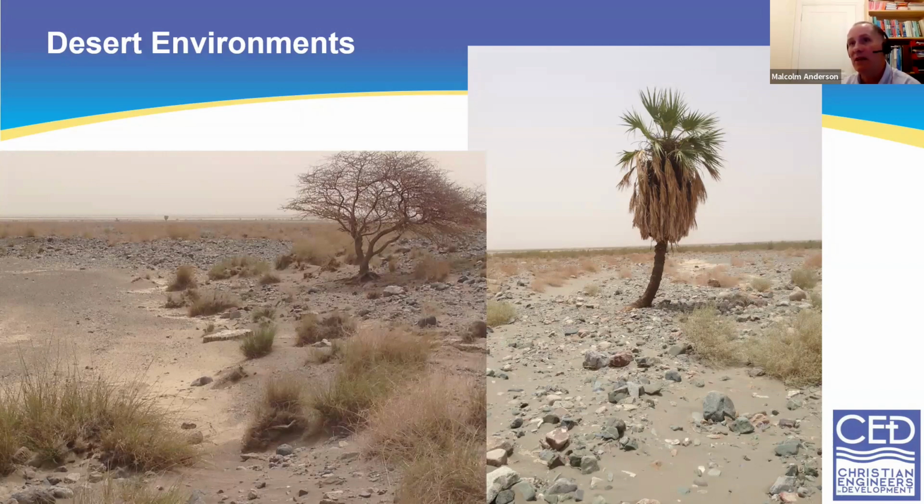I know that in this location on the right, groundwater level is likely to be close to ground surface. Just because this tree here and the environment here is such that they only get 2 or 3 good rainfall events a year and runoff events. So it would be difficult for that tree to survive unless the groundwater was close to ground surface and isn't too salty. Whereas with the acacia tree, it doesn't tell me too much, but it probably tells me that the groundwater level is quite a lot deeper.